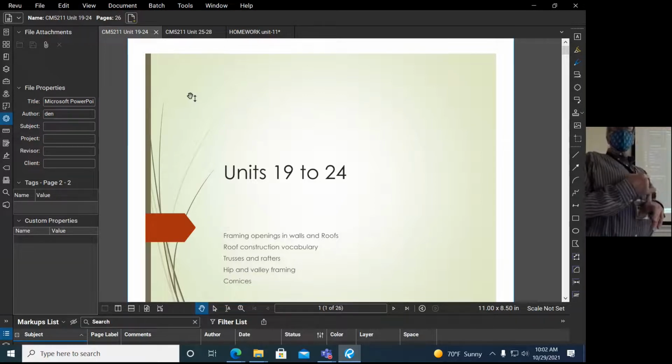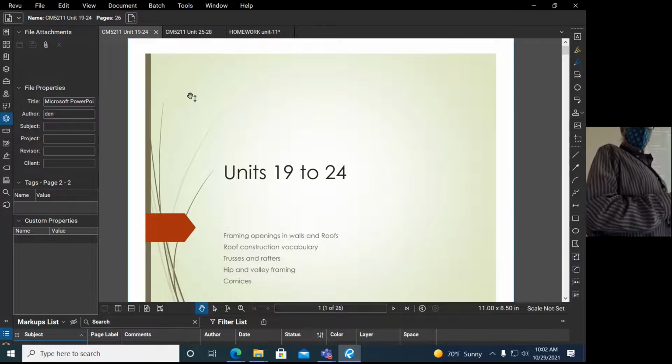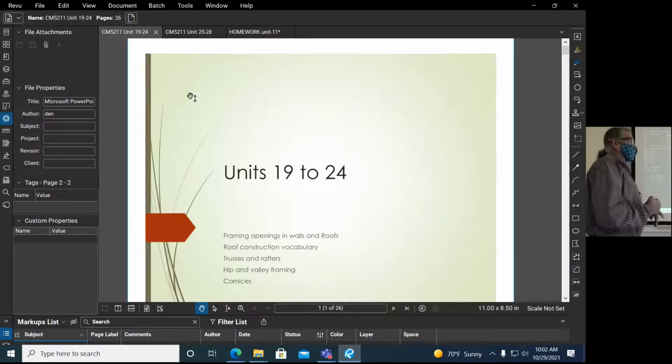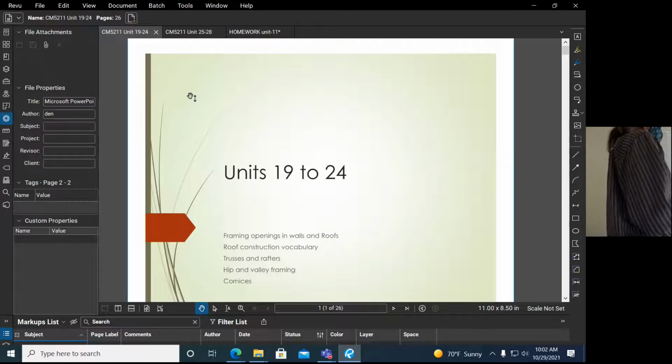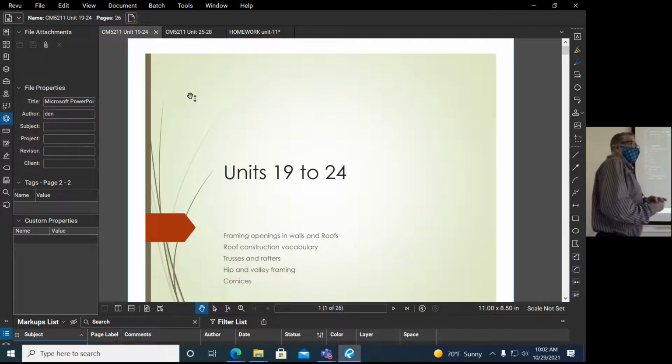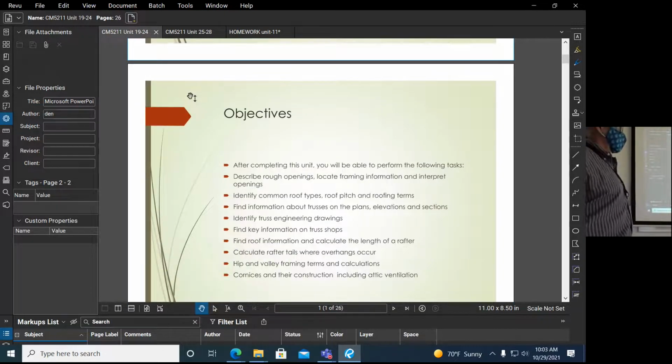So framing. So framing is the underneath skeleton of the building. So in the case of wood, it's 2x4s and 2x6s, and then other kind of truss elements or truss joist elements, LVL elements, and it also has to do with the metal pieces that tie all that together as well. So in California, we have a lot of metallic connectors to connect it to the foundation, and then to connect all of the framing pieces together with each other to keep it from shaking apart in an earthquake, basically. So we have to do extra kind of connections.